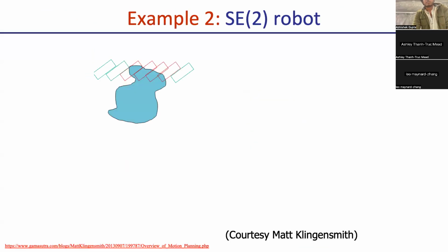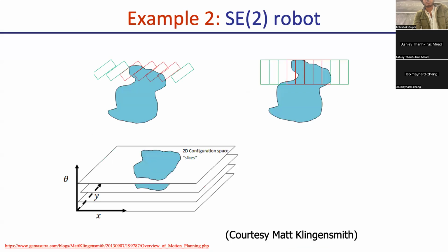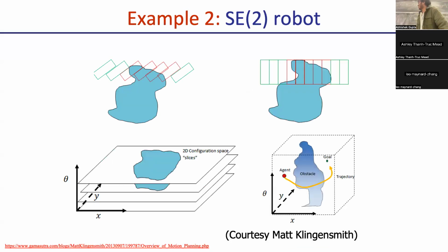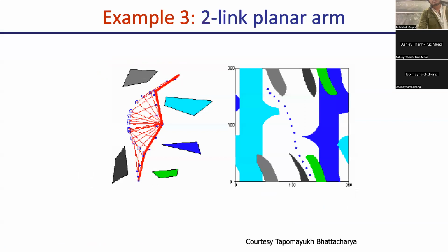You can do the same thing for a rectangle. It looks like that. And for a more nasty looking obstacle, you get some weird 3D shapes. It's often pretty counterintuitive to do this, and you often won't actually do this explicitly, but it's more for visualization. Part of what makes motion planning so hard is that mapping configuration and world space together is a non-trivial exercise. Let's take a look at some examples from different arms.